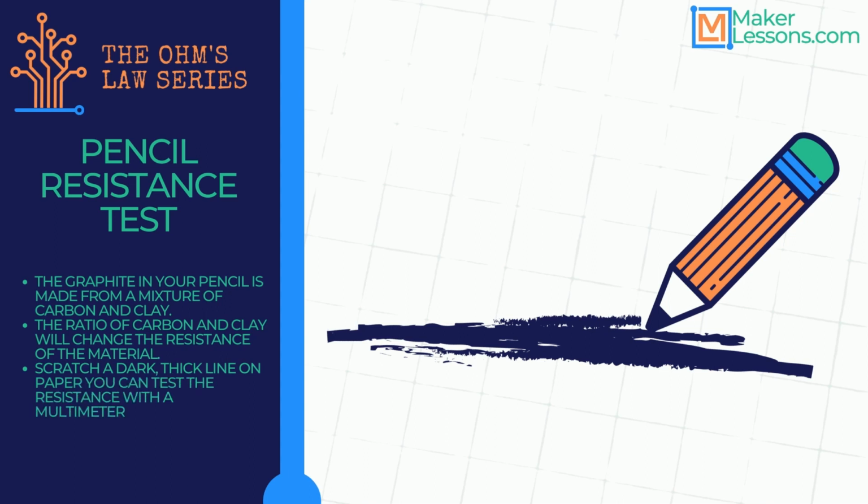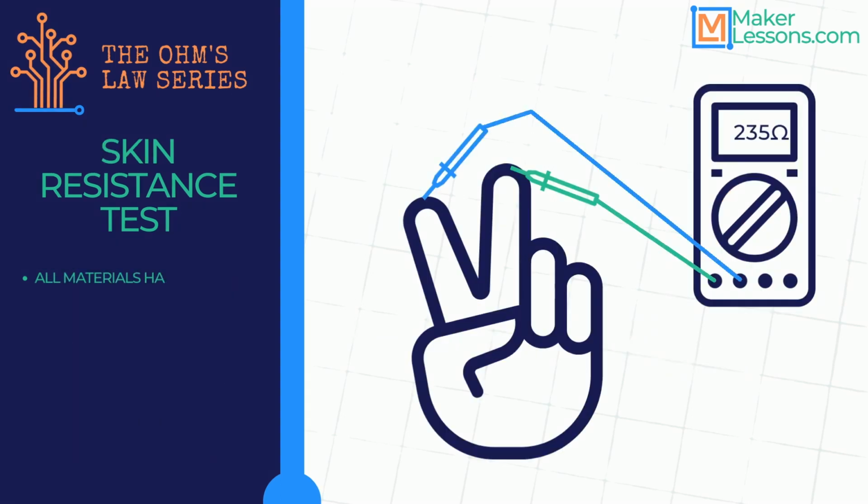This is actually the same material that is used in some of our resistors. If you scratch a dark, thick line on paper using your pencil, you can test the resistance of the line with a multimeter. Change the thickness and length of the line for different resistances. This is the same as if you were to change the length or diameter of our pipe in the water analogy.